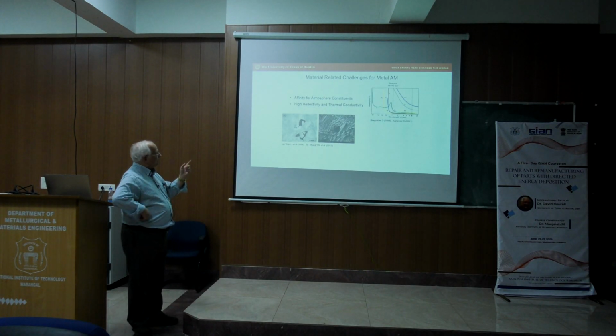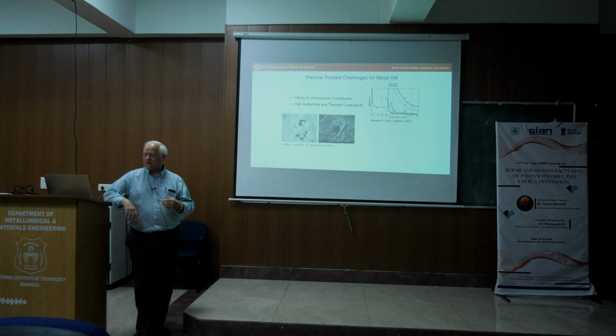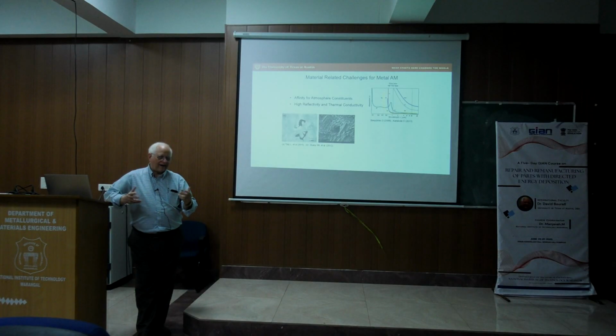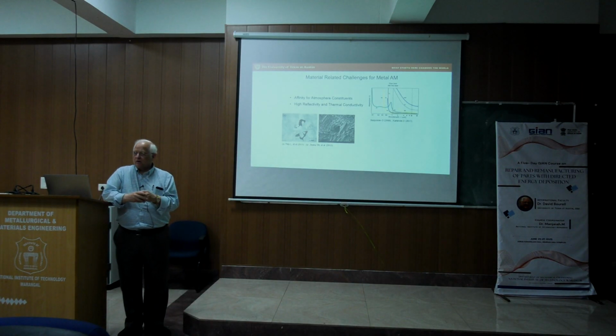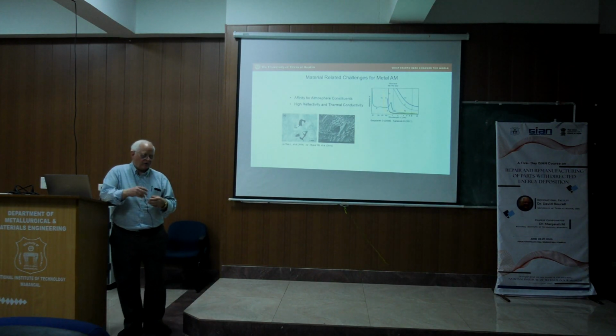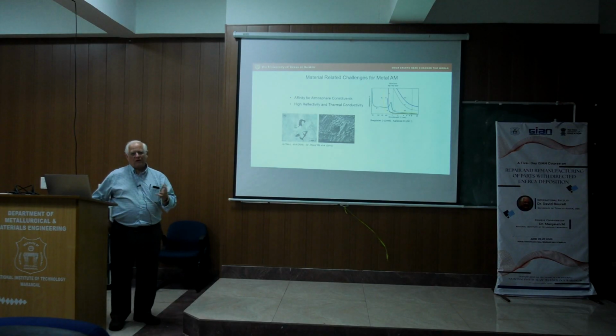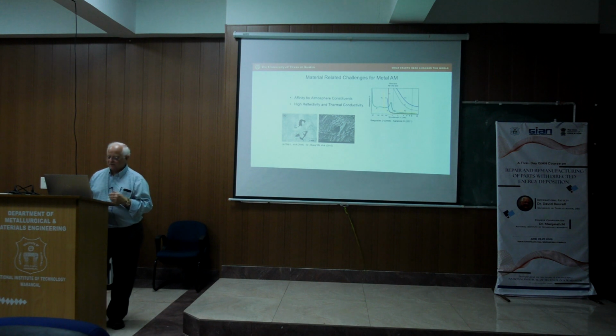But in all the cases, we do have to worry about thermal conductivity and heat conduction, because what we would like, ideally, is for the energy to form the melt pool and for it to flow a little bit to form the bulk of the part. But if the thermal conductivity is high, the heat conducts away very quickly in the solid state, so we don't have that concentrated heat source as much as we would otherwise. So thermal conductivity can have an effect as well on the challenges.